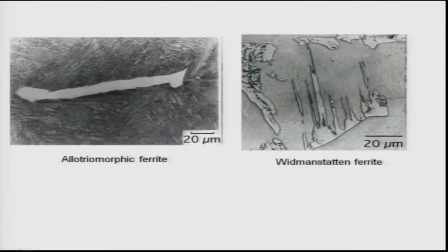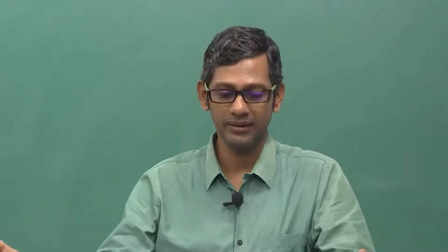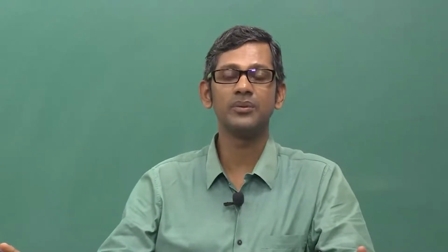But you know, we always have hypo or hypereutectoid steels, which will also transform into pearlite, but it will transform into something else plus pearlite. So, if it is a hypoeutectoid steel, you can have ferrite as a primary phase. That is obvious from the phase diagram. Let us not discuss again the same stuff, but if it is higher than 0.8% carbon, it will lead to hypereutectoid steel. Therefore, the primary phase will be cementite.